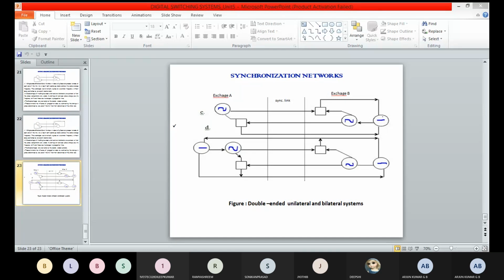Again, the asynchronous network for an integrated digital network. Since this is an auxiliary network, it must link all the exchanges in an IDN. Then the synchronous network has the same nodes and the same hierarchy structure as the parent public telephone exchange, that's the PSTN. The synchronous links are provided by the PCM system that carries the normal traffic between the exchanges.